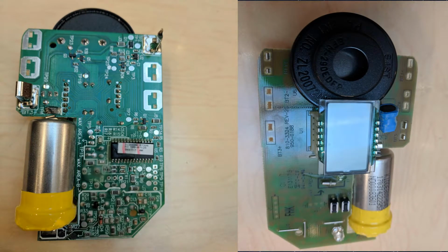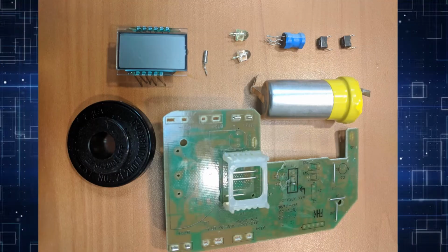The next part of our product case study is analyzing the printed circuit board. On the lead side of the PCB board are small surface mounted components such as a microchip. On the insertion side of the PCB board are through-hole mounted components such as an LCD display panel or transistor. The multiple through-hole components suggest wave soldering was likely used. Also, the low thermal resistance of the through-hole components is another important indicator that wave soldering was used for these components, as they could not withstand the heat of a reflow oven.